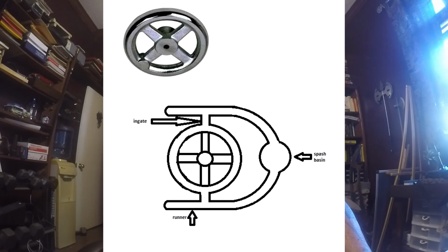And you would put the riser on that, all right, to feed that central hub. The rest of it would solidify pretty quickly, and that central hub might even feed the rest of it before it solidifies and draws the molten metal from the riser. The drawing that you have below is the way I would feed that.